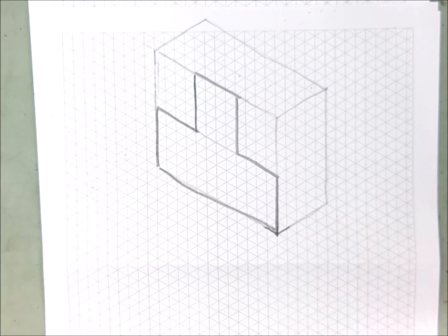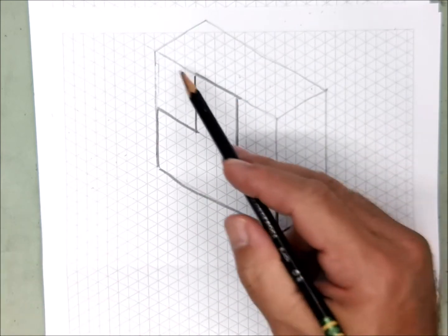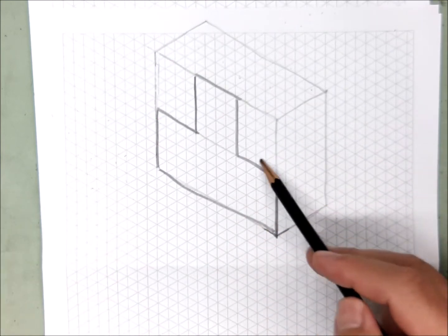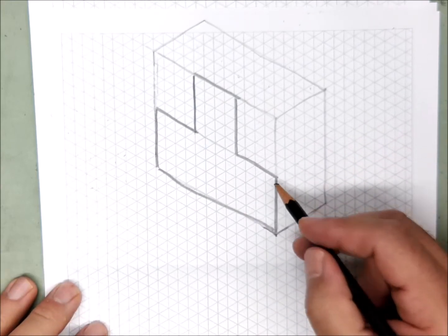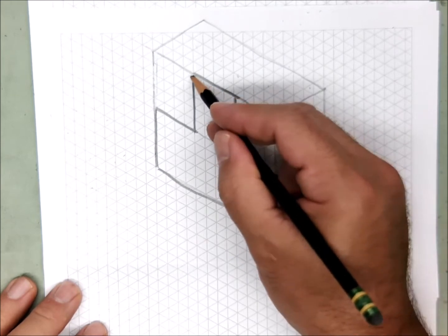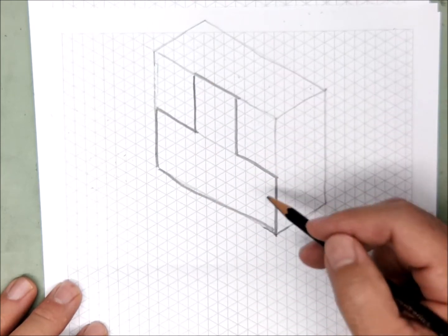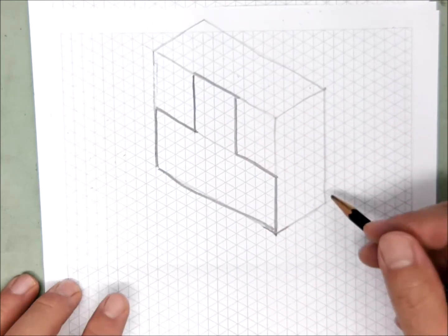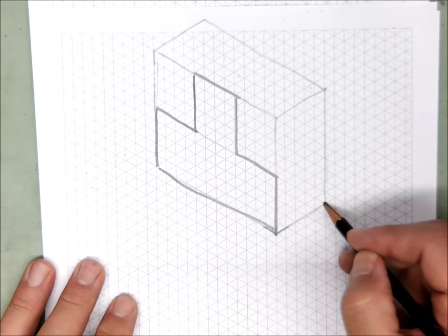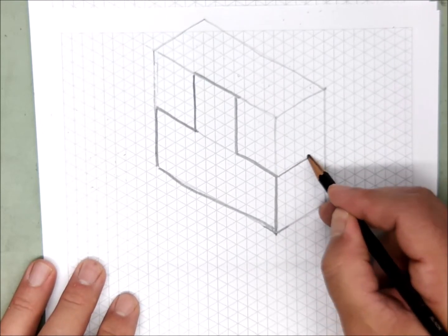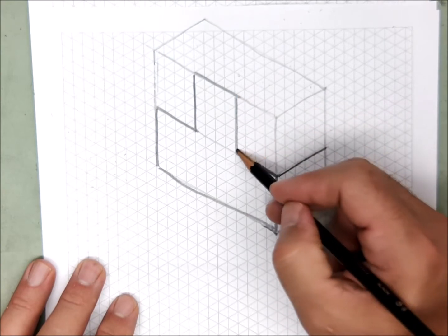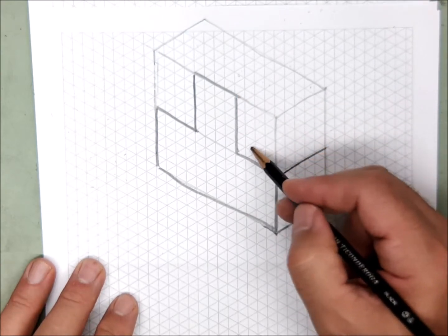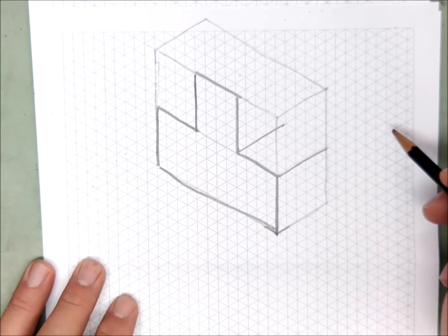But if we just leave it like this, it looks like someone took a rectangular prism and painted those lines on the front of it. Doesn't look 3D yet. So remember what we need to do? All of these new corners we've added need to project back either up to the right or up to the left. This corner at the bottom went up to the right, which means the corner above it will go up to the right. This corner here goes up to the right, which means this corner will go back the same amount up to the right.